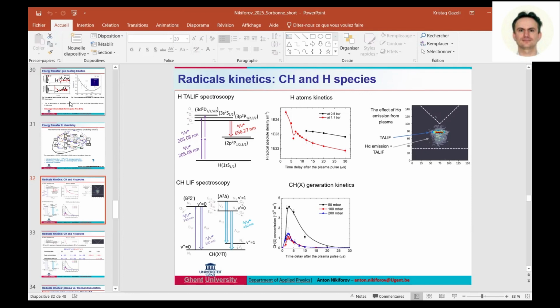This is what we also have. And now we are moving to heavy hydrocarbons like styrene, which we also want to decompose by the same process. We not only have a formation of soot in the reactor here, but it also starts to form some kind of wires from one electrode, and in a matter of half an hour, it reaches the second electrode. So it's some kind of tiny filament of carbon, which goes between 2 electrodes, and basically then it makes a short arc between electrodes. This is another problem that we have to solve.